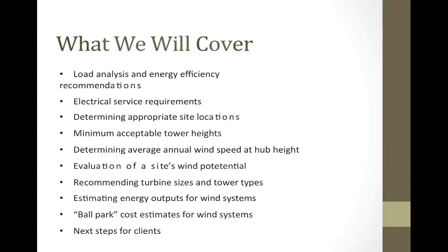First thing we put is load analysis and energy efficiency recommendations. Why would we do that? Well, as you remember from earlier in the class, if I can reduce the amount of energy I need, I can get by with putting in a smaller turbine. We have to talk about the electric service requirements. What do we actually need? How do I connect to the grid near me? Is it a single phase voltage? Is it a three-phase voltage? Is it getting to my home overhead, or is it underground?